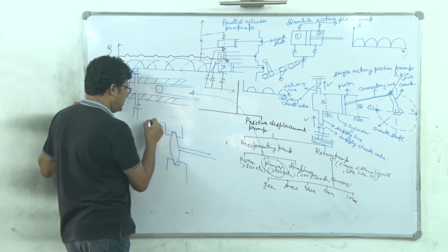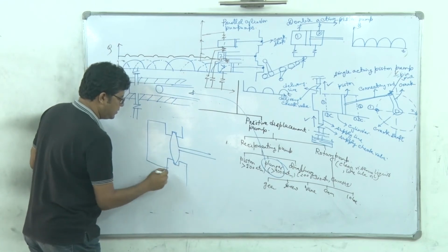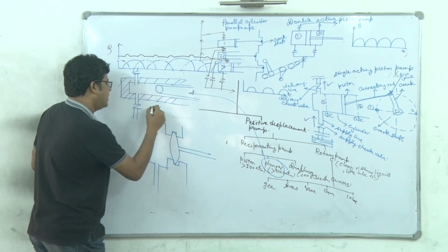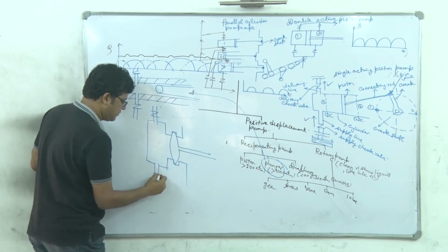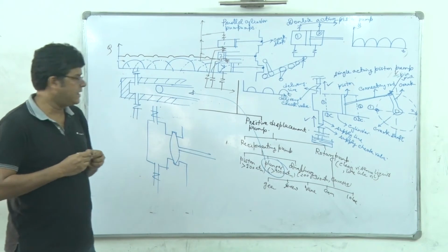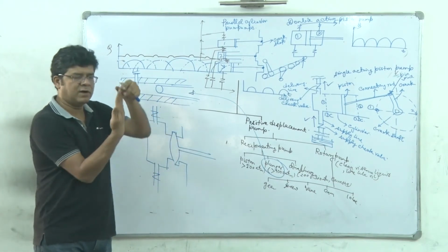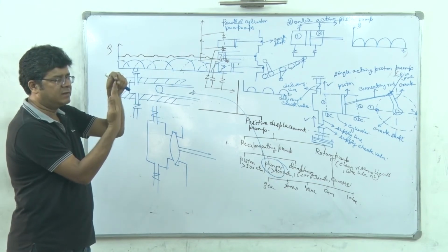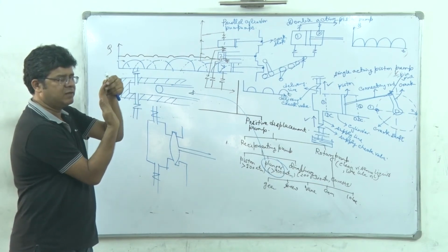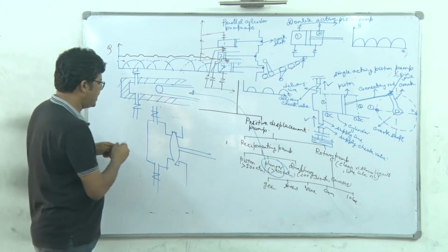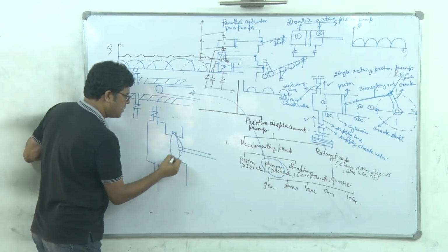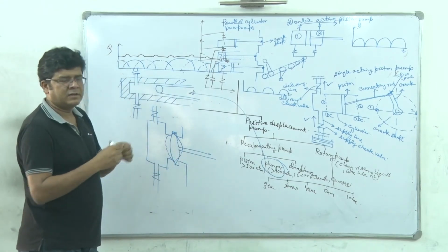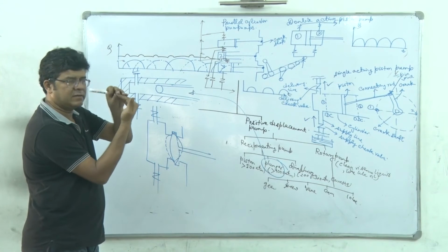Here we have the suction line and the delivery line, both fitted with check valves. Just like it's fixed at the groove, whenever it is operating in the suction stroke, it will assume a shape like this, convex backward, and whenever it is discharging, its shape will be like this. So it will just move like this.